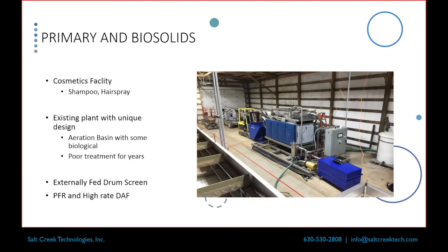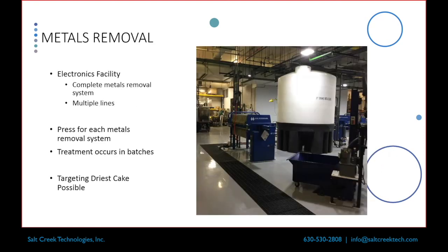The DAF is a little bit less loaded, but still providing what needs to happen. So I think it's illustrative of how important considering sludge hauling costs are, especially when you're dealing with just a DAF. A lot of plants will just take a DAF sludge and plan on hauling that. But sludge hauling can get pretty costly. It's something that you really want to think about sometimes, depending on your location.